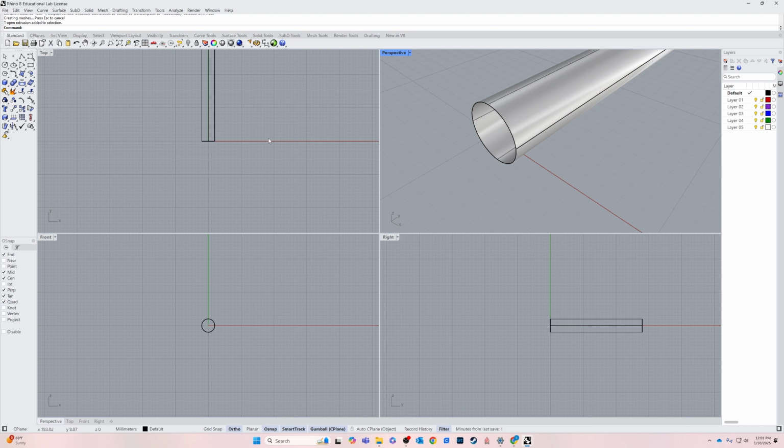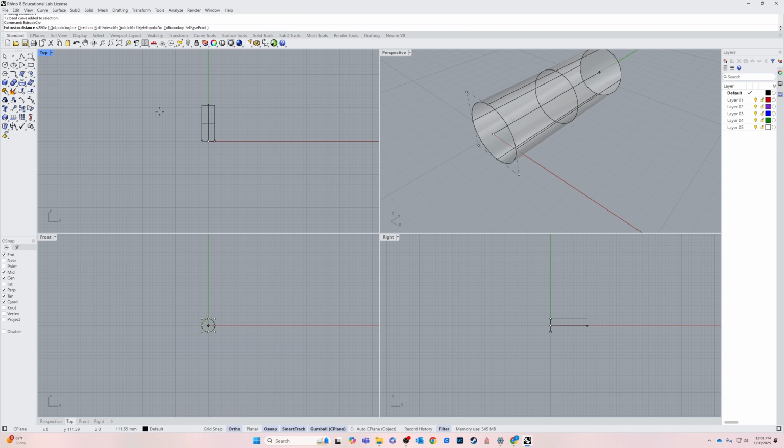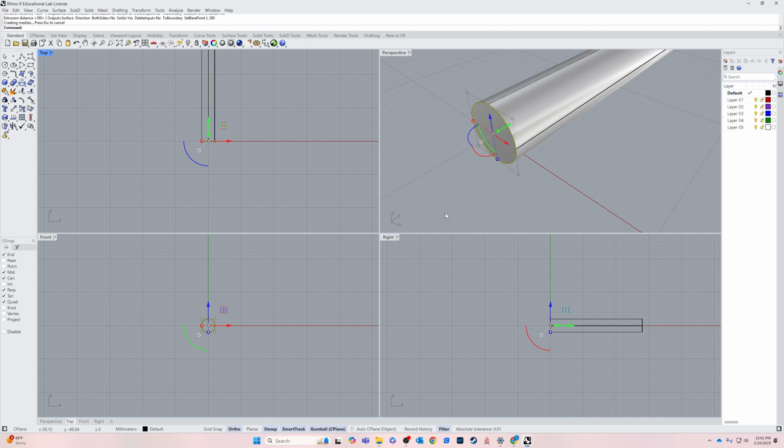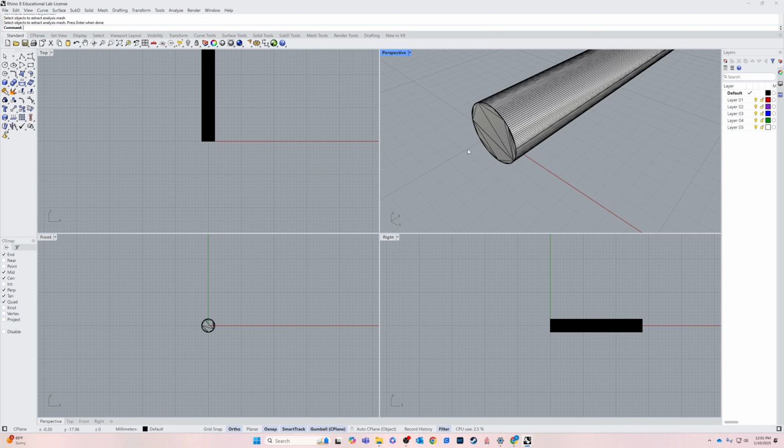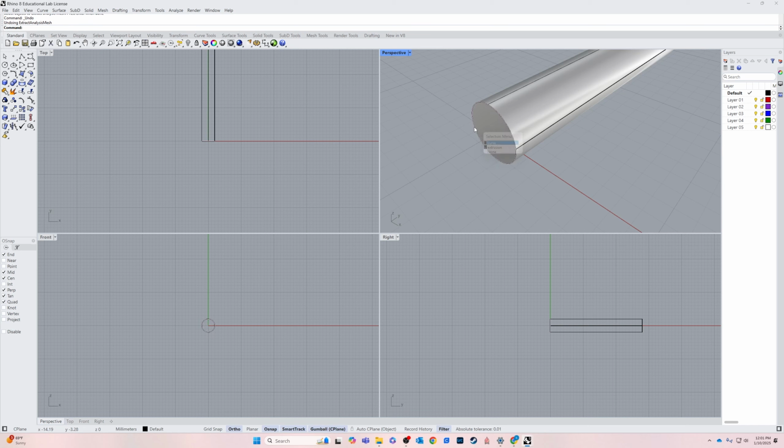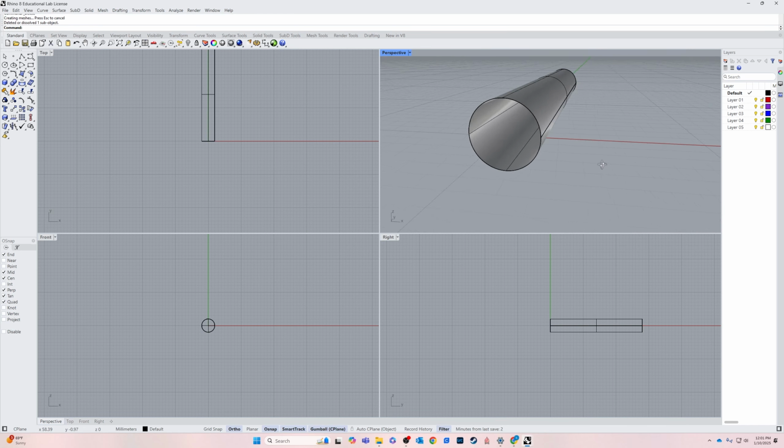The reason for that is sometimes it thinks you might want to use surfaces. But if I type the extrude command, select the object, and turn solid to yes, it'll now make it solid, 280, enter. So that's sticky. That's an important thing to remember, because if you're ever extruding things and they come out as surfaces instead of solids, and of course what I mean by that is this face is basically off of there, and I can see into it.